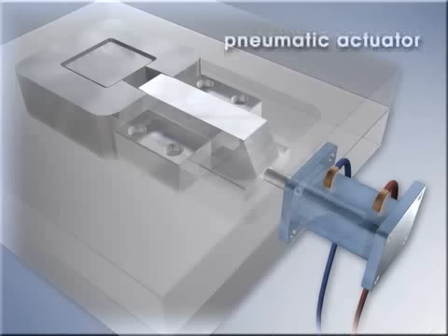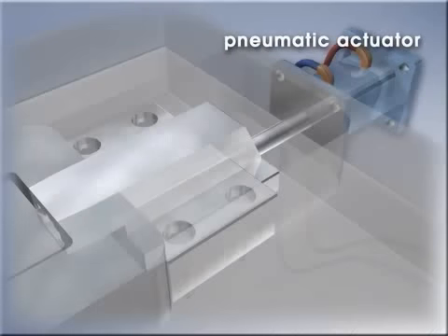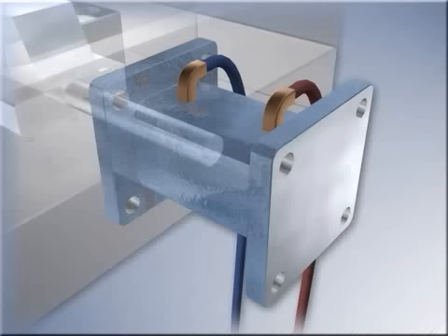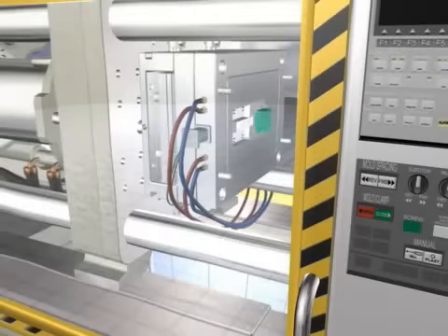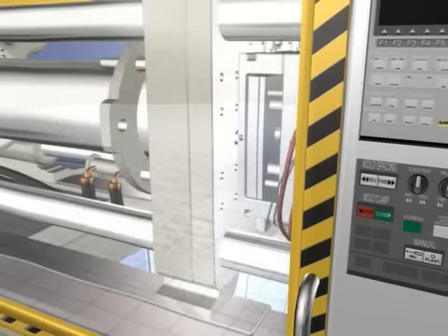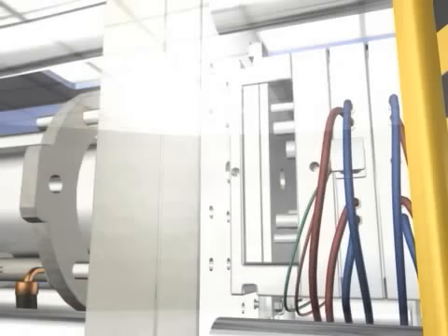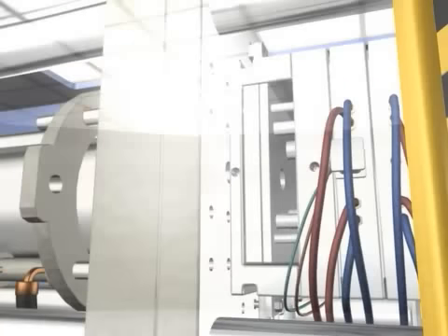Pneumatic actuators use an air-powered cylinder to move the slide back and forth. To control the pneumatic cylinder, an auxiliary function on the machine or a pneumatic pump linked with the machine is required. These systems can actuate the slide faster than the mechanical method and induce less wear on the slide assembly. Pneumatic actuators are ideal for high-speed applications, in which the slide has little detail and can be easily pulled from the part.